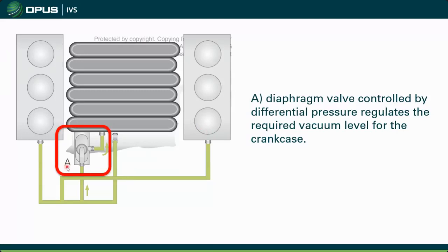Those hoses came together and vented into the intake manifold through what they call a differential pressure regulator, or a pressure regulating valve. That's basically going to control the flow of those gases so that you're not putting them in the engine at the wrong time. Because you don't want to create misfires or drivability issues, because that's going to drive up emissions. And of course, that's not what we're trying to do here. We're trying to do the opposite.